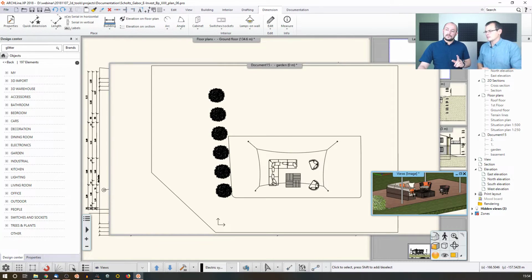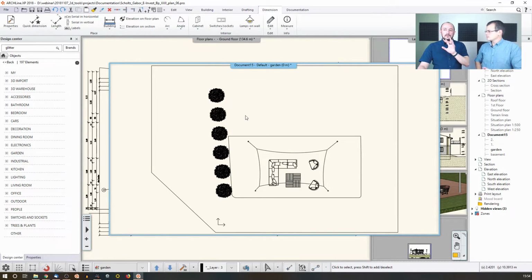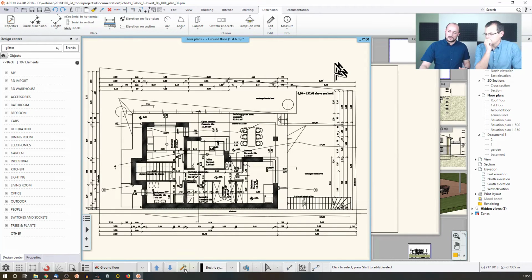Same thing. So now, actually, from this point on, it's important to talk about how the software generates the 3D, because now I actually have two different drawings in one single project. So this is how you can control that. If you click on the other drawing and hit the 3D hammer, you will build up this part of your project and not the other one. The other one will be thrown away, but you can regenerate it anytime you want. So at any time you can just switch between the two.